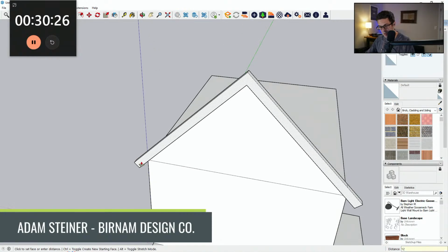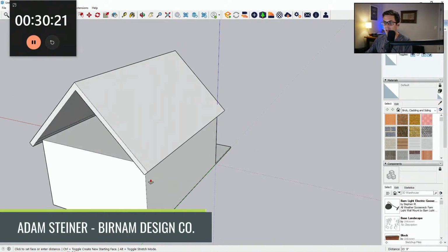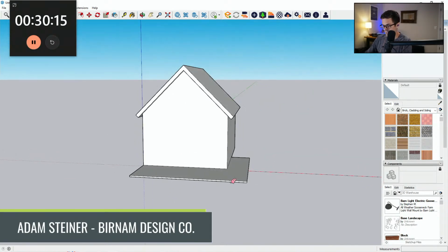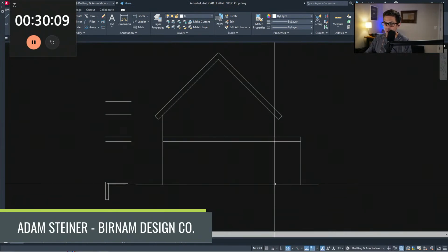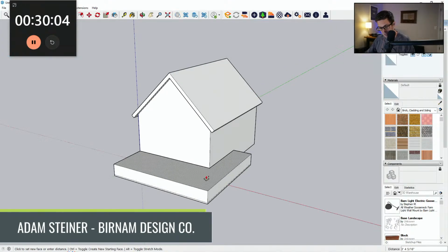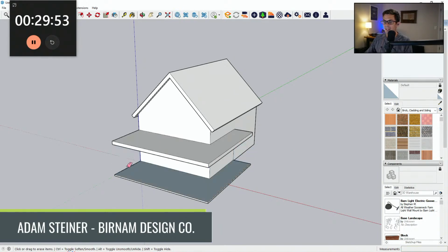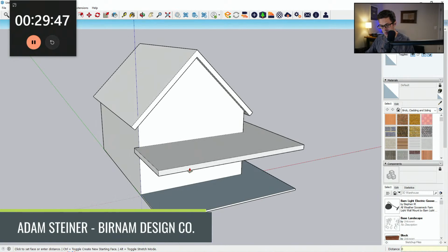Okay, let's come out a foot. And then let's go back with this as well, all the way the length of our cabin. Okay, and then that porch roof is going to come up above grade 9'9" and an eighth, so 9'5" and an eighth above our slab. 9'5" and an eighth above our slab, and that again is going to be a chunky boy. Gonna delete all that. Okay. Then I want to overhang a foot each way.